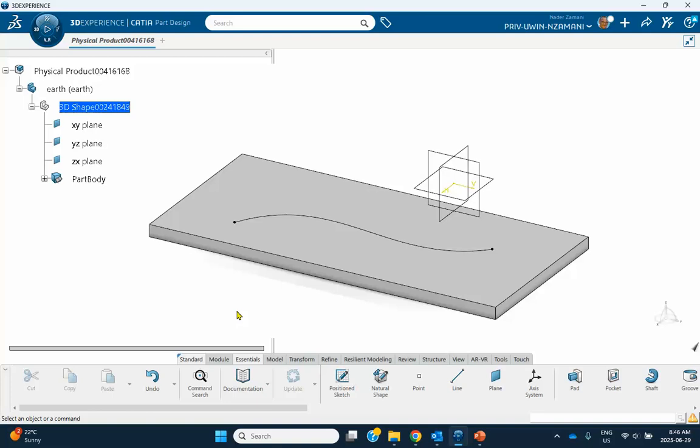But it looks like they have done things here in motion design so that when I do the engineering connection here, it doesn't matter. When I try to do a roll curve joint, it'll bring it and just make it tangent. So that step that I did in tutorials 9 and 10 is unnecessary here.